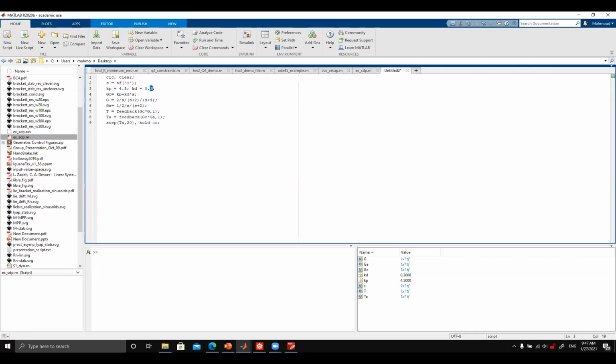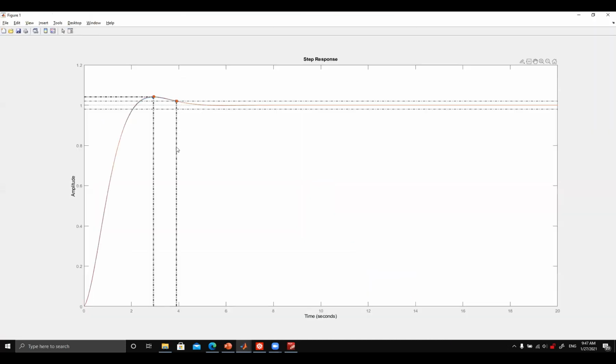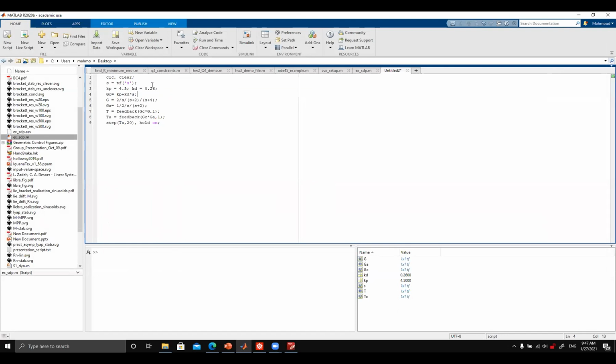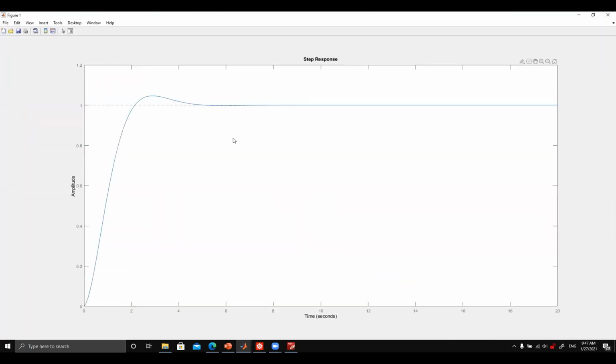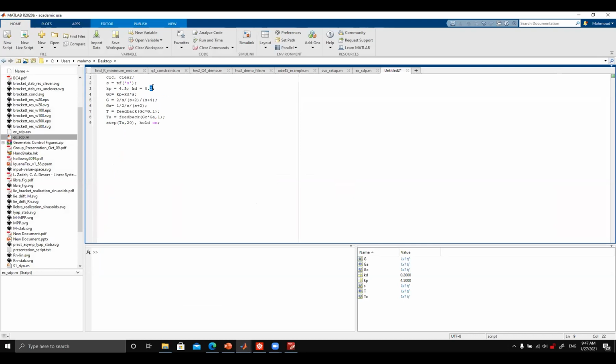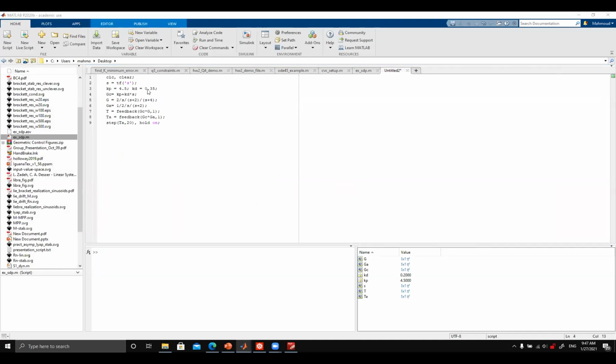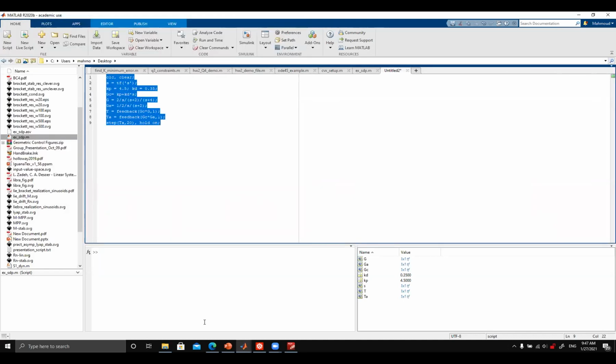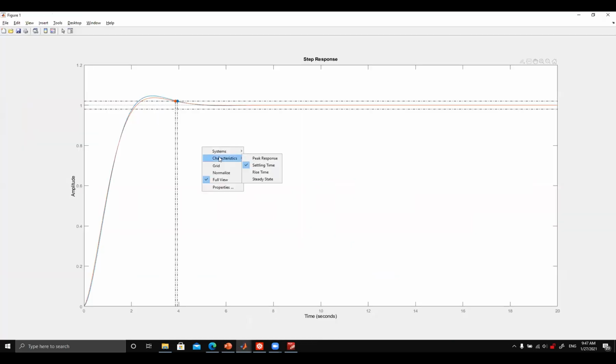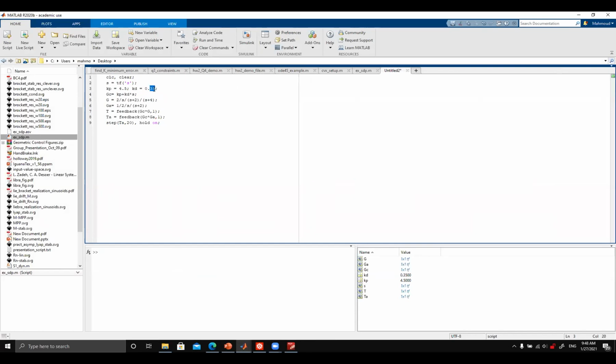So that, or maybe decrease this a little bit, KD, because as we know that, so let's see if this works. Well, not a lot of difference. Maybe if we make it 0.2. Oh, we should actually increase it. Sorry, 0.35. 0.86. If we make it 0.4, we should get a better response.